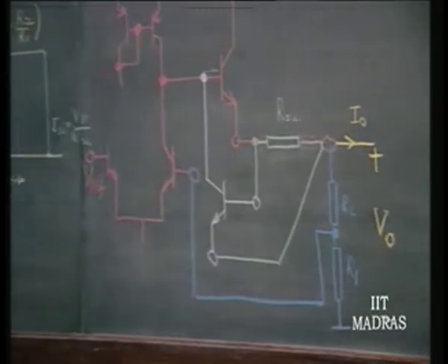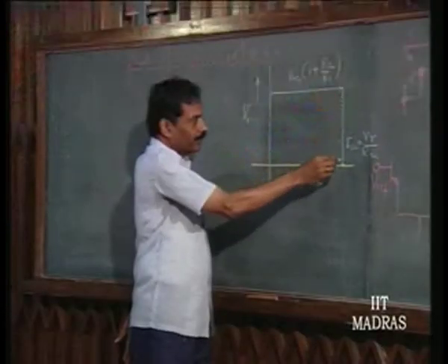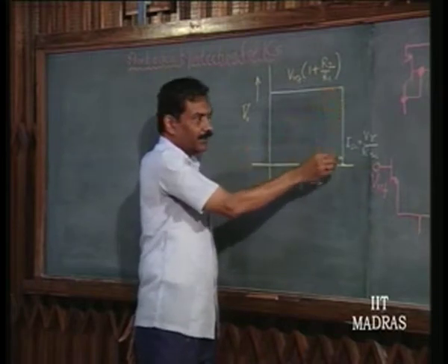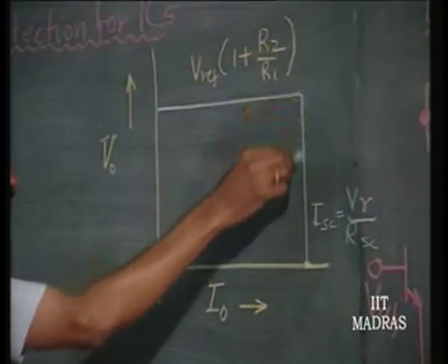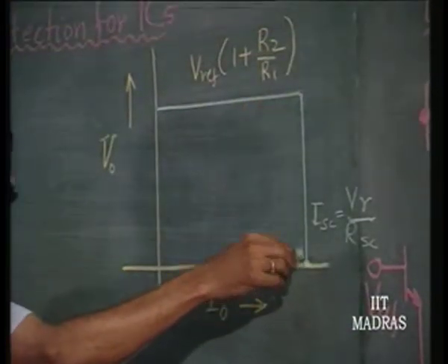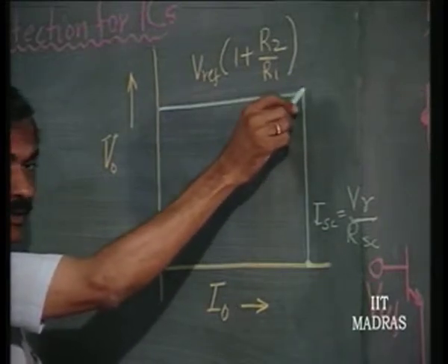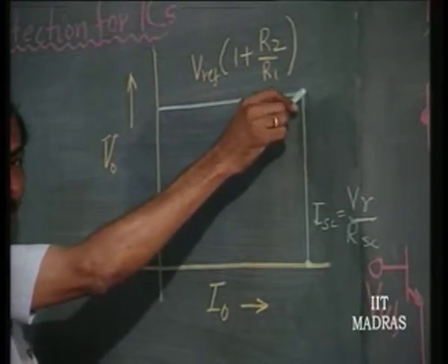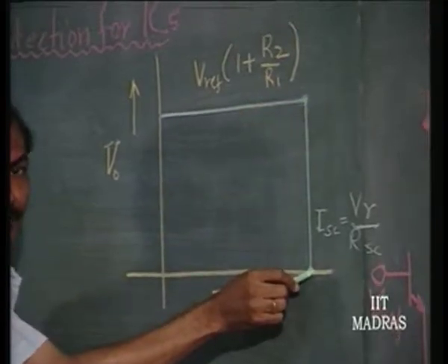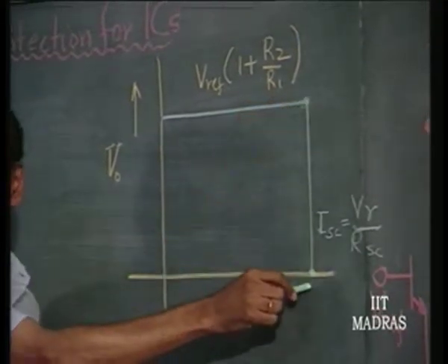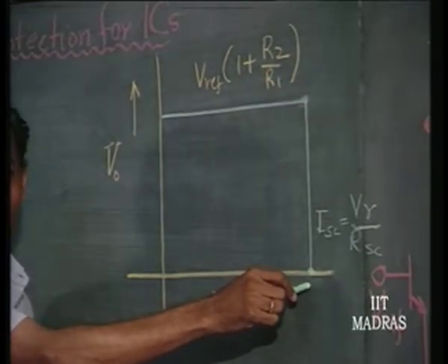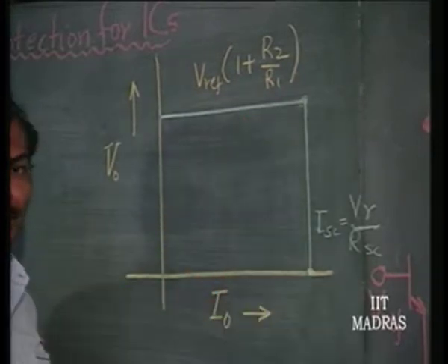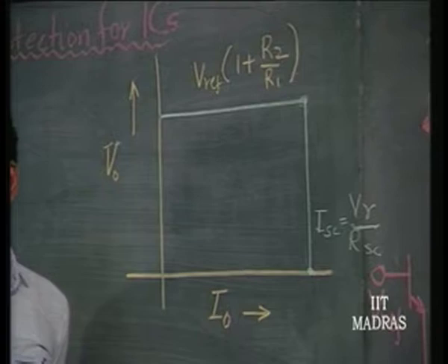Now, that kind of short circuit protection results in the voltage source being converted into a current source thereafter, and therefore, the current is going to remain constant. We found that the power dissipation under that situation in the IC is lowest at this point, but highest at this point. So, it gradually increases from this point to this point, and nobody can guarantee us what exactly is going to be our short circuit situation, and therefore, this kind of situation is not a good thing for the IC.